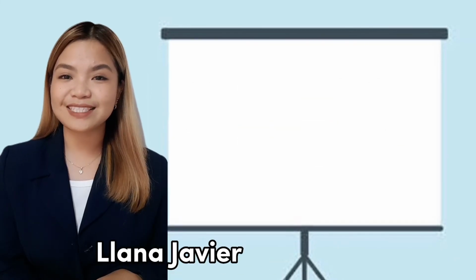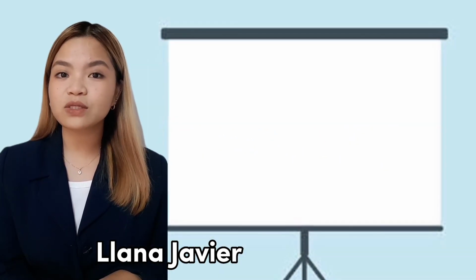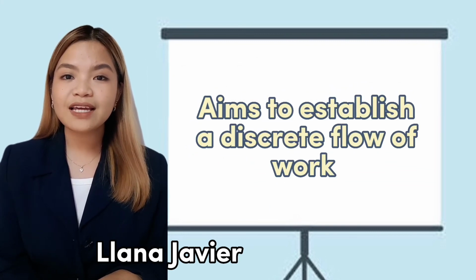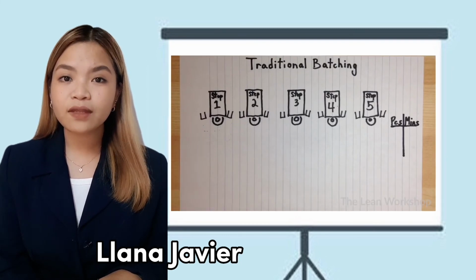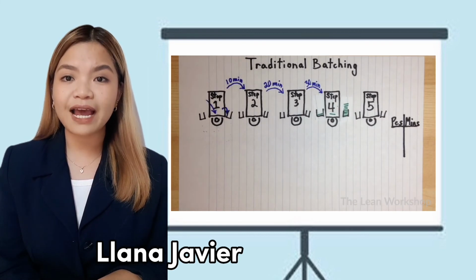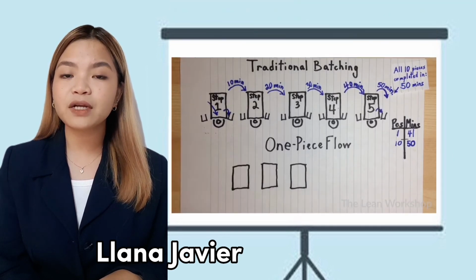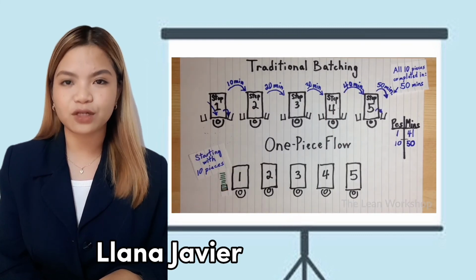Here now we will be presenting about single-piece flow. One-piece flow, sometimes called continuous flow or single-piece flow, is a lean manufacturing concept that aims to establish a discrete flow of work in contrast to the typical mass production strategy. In mass production, materials move through the manufacturing process in batches, which can be highly inefficient. In one-piece flow, a product is completed before the next one is started. It is typically used in lean organizations and will help businesses achieve just-in-time production.